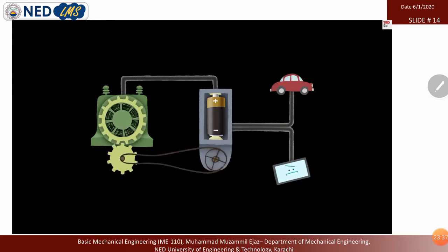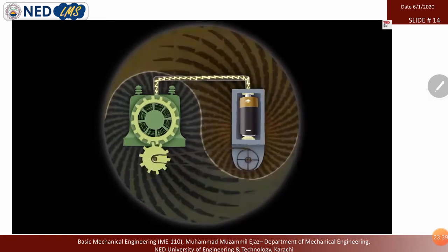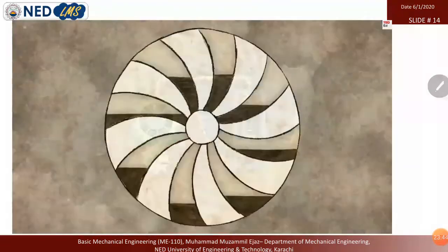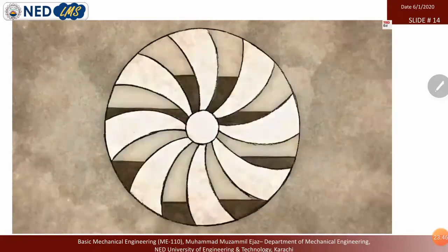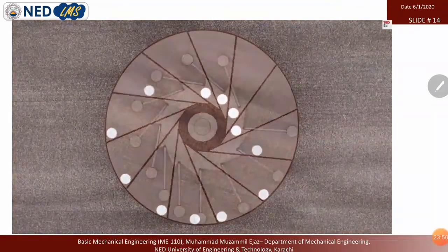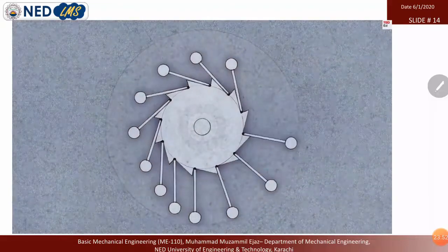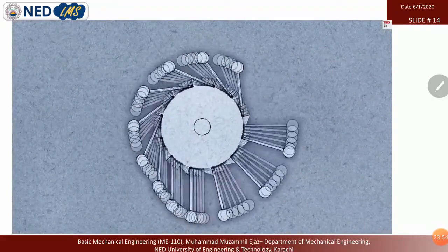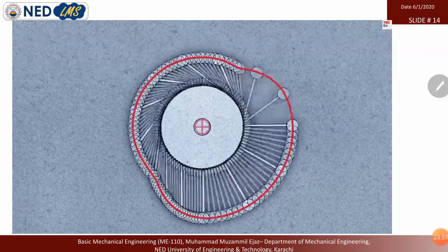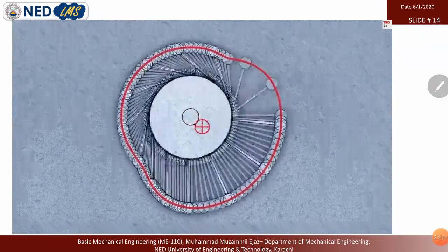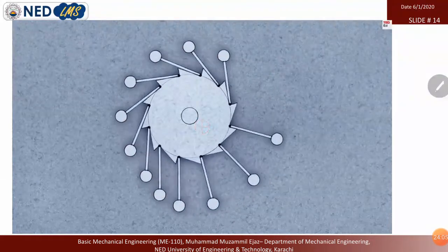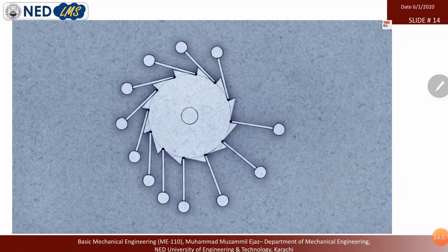But what if you just wanted the machine to keep itself moving? Inventors have proposed plenty of ideas. Several of these have been variations on Bhaskara's overbalanced wheel, with rolling balls or weights on swinging arms. None of them work. The moving parts that make one side of the wheel heavier also shift its center of mass downward below the axle. With a low center of mass, the wheel just swings back and forth like a pendulum, then stops.